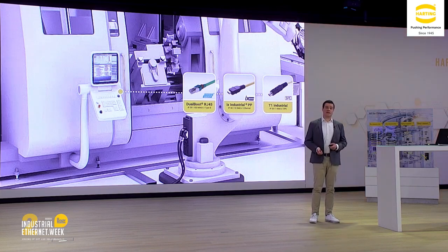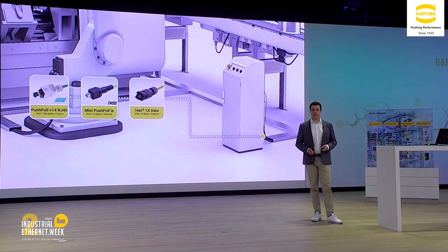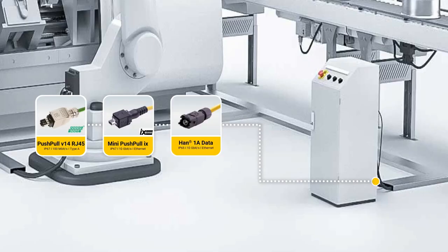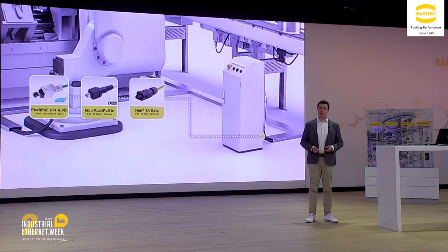But you don't have only the IP20 area, you also have different cabinets in the field where maybe IP65, 67 are needed. And if you don't want to go with your complete cable assembly into this separate box or switch cabinet, you also have the possibility to create a pluggable interface and have a connection only for this switch cabinet. Here, our IP65, 67 solutions are possible.